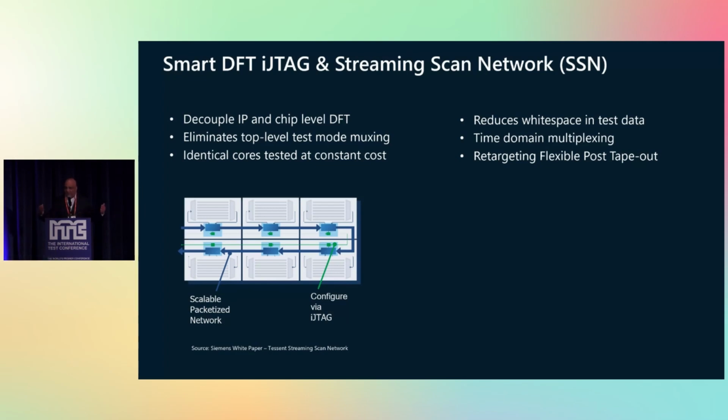As long as I used a method that was floor plan aware and I ended up routing it, I could bring this up and make very, very late changes, right? There will always be changes, like this portion of the floor plan is going to move from north to south, east to west, and vice versa, and DFT has to react to it overnight or in a few days kind of situation. And this is very common. This trend is very, very common, right?